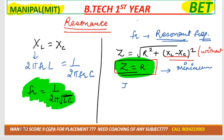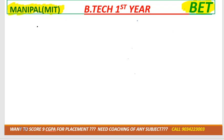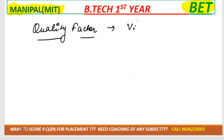And if impedance is minimum, then current would be maximum, right? So maybe they'll give it directly to you that this is the case of resonance, or maybe they'll give it indirectly, that Z is minimum. So you have to understand that it is a resonance case, or they'll say I is maximum, or they'll ask you the quality factor. Whenever they ask you the quality factor, that is the condition of resonance only.